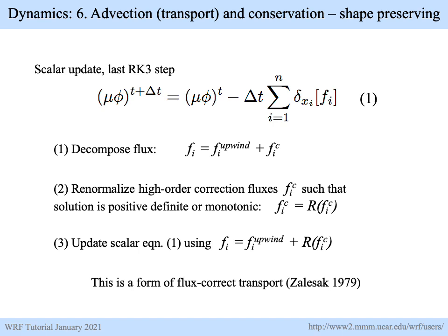We can decompose those fluxes into a pure upwind flux, which is a first-order scheme, which just says take the mass from the upwind cell, just that, and not that more complex formula I showed you earlier for the higher-order schemes. We can decompose it into a correction in that upwind thing, and that correction being the full flux we just computed minus the upwind.